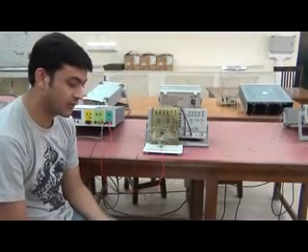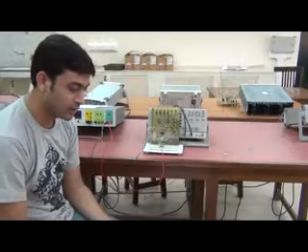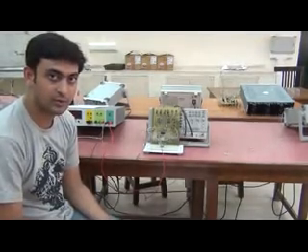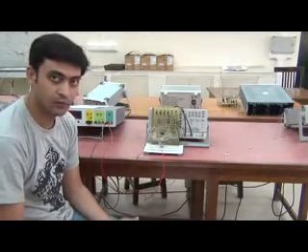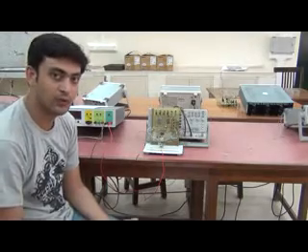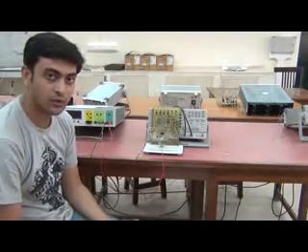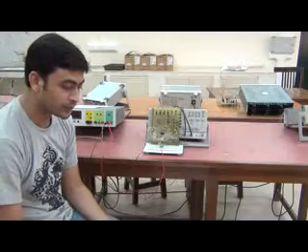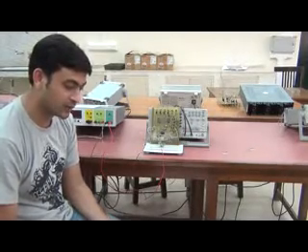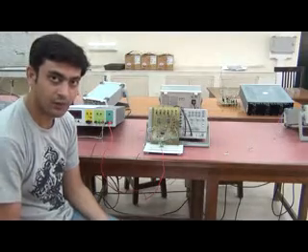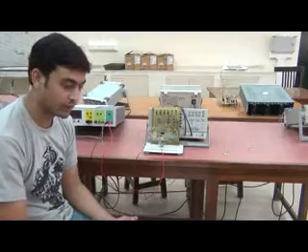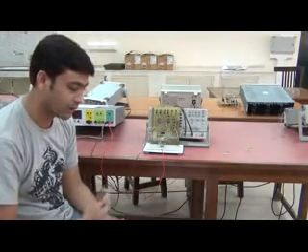The design table for this divide by 4 synchronous down counter will be as follows, as it will be given in the handout. From 1 1 it will move to the 1 0 state, from 1 0 it will go to the 0 1 state, and from 0 1 it should go to the all 0 state. So depending on this output condition, the inputs of the flip-flops will be set so that we can observe this particular sequence in decreasing order.